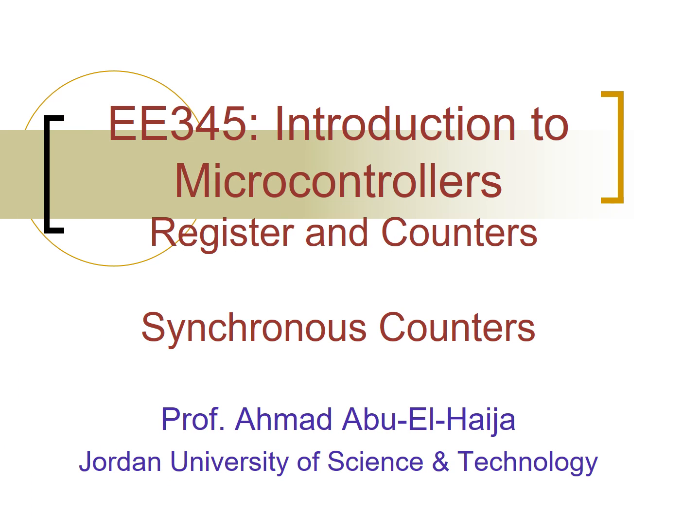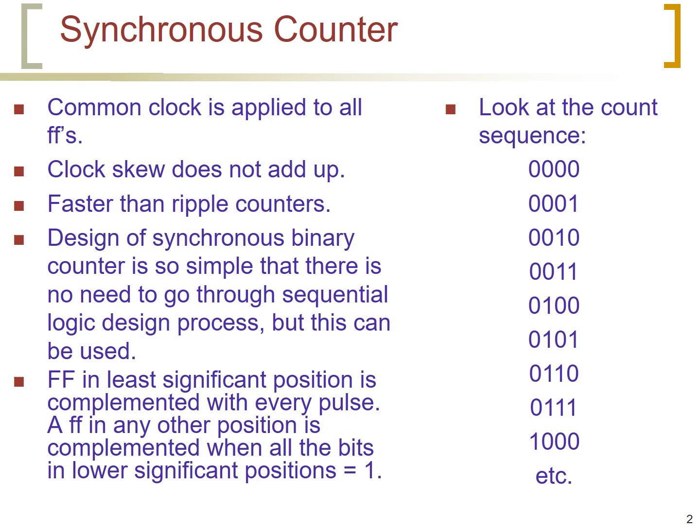In this video, we present the design of synchronous binary counters. A synchronous counter usually has a common clock that is applied to all flip-flops, and that's where the word synchronous came from, because the flip-flops are synchronized through the clock. This is different from the ripple counter because the clock skew does not add up.